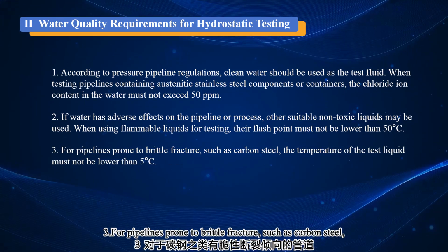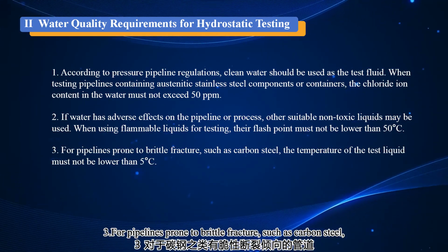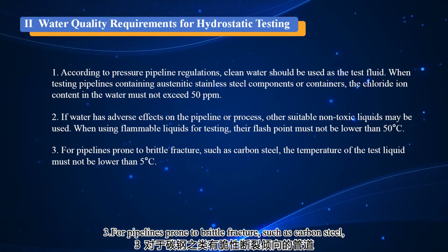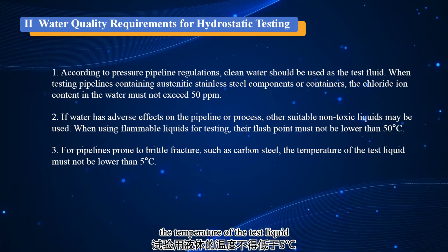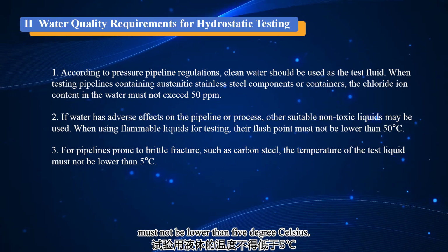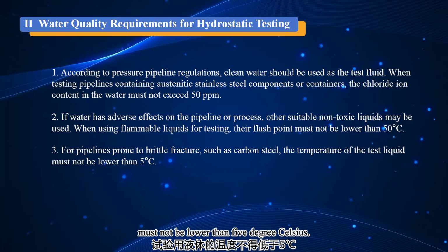Third, for pipelines prone to brittle fracture, such as carbon steel, the temperature of the test liquid must not be lower than 5 degrees Celsius.